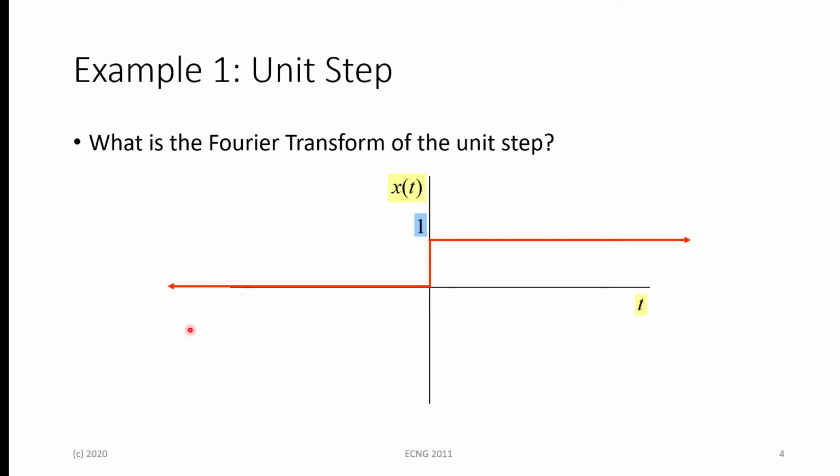So, because we're going to be focusing on the use of the Fourier transform, and we saw the Fourier transform with respect to the unit impulse and then the rectangular pulse in yesterday's lecture, we're going to be focusing on a little more of a practical signal here, and in this case we're going to be looking at the Fourier transform of the unit step.